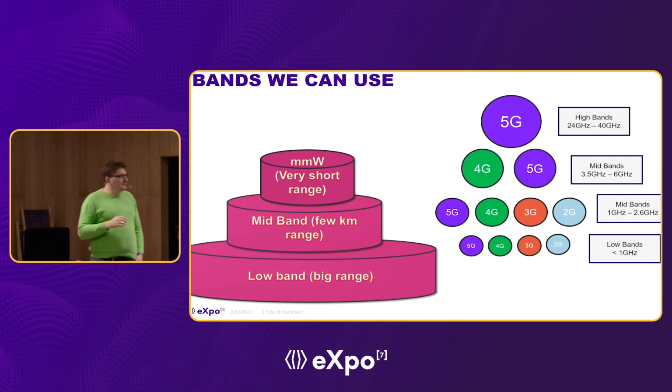There is also one additional info here. It's a bit deep, but treat it as something to tell your friends during the coffee. When you're sending the waves in any telecommunication, you are using something that is called inverse Fourier transformation. It's a mathematical equation to go from the frequency to the time domain. And to use this mathematical equation, you are picking the points on your radio frame for each subframe you are sending. And by increasing the spacing, we are generating less amount of subframes. So we need less amount of these points to make a Fourier transformation.